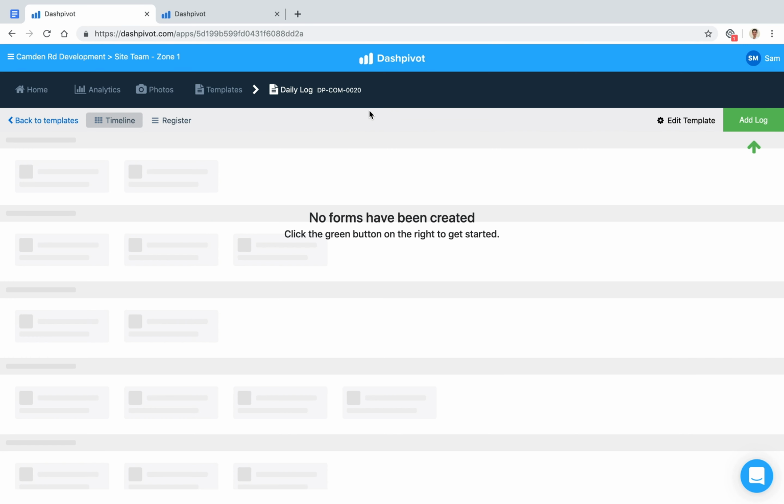A construction log is a daily or weekly record of all the key activities occurring on site, typically filled out by the foreman or supervisor, though sometimes there's input from engineers as well. It contains details about site conditions, about work activities, who was on site, what equipment was used on site, records of material deliveries, any incidents, any delays, as well as progress photos.